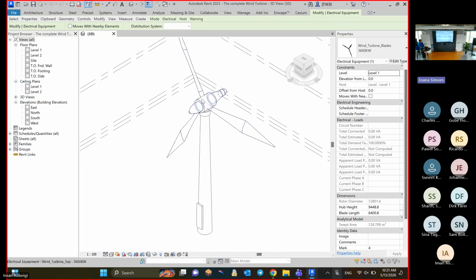So after this, I could install the Cesium. Cesium is the best converter tool, as I could understand, for converting this 3D model to GLTF and 3D tiles. The difference between GLTF and 3D tiles, as I understood, is that 3D tiles contain different kinds of GLTF models, and we use that 3D tiles model to upload this heavy model.